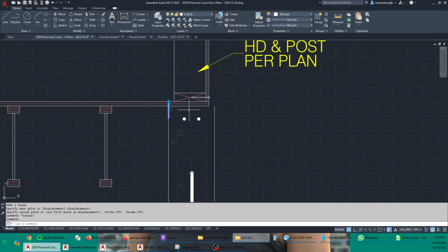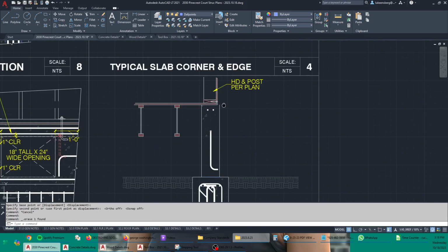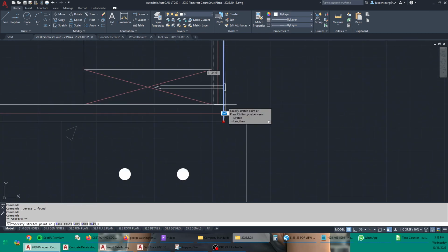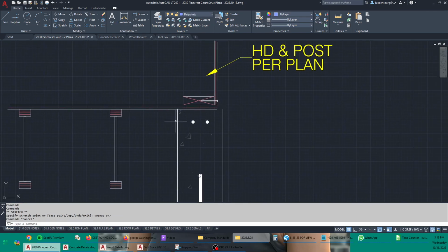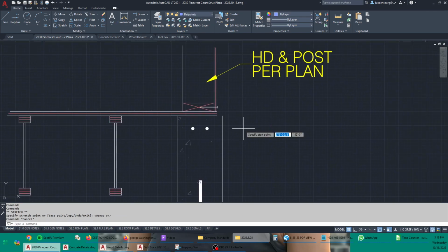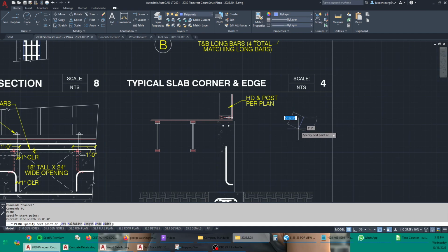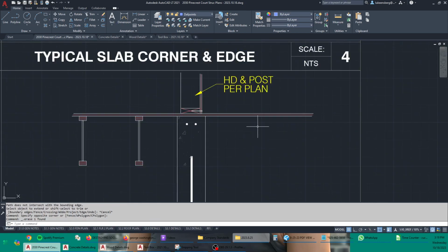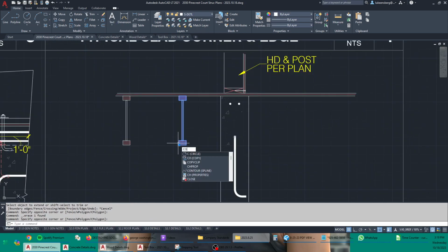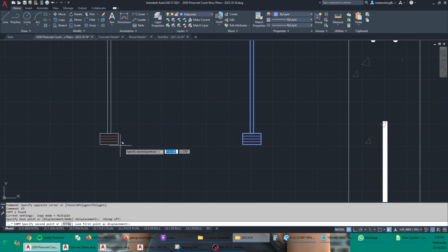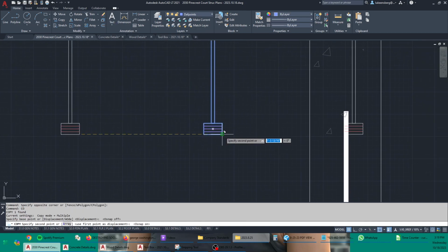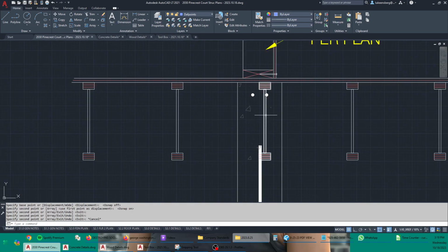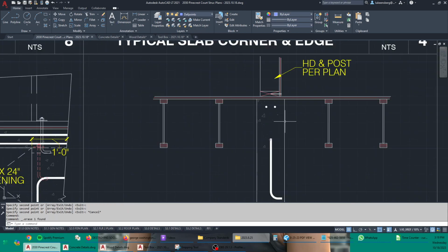This, we don't need that. And then this, let's move this up. The floor sheathing. Remember I said there's floor framing on both sides of the wall, so I'll extend out to that drawing aid I just made, boom. Right, and then we'll copy some more joists. I'm going to use the previously existing joist spacing to help me copy over, right? Those are all 16-inch like that. And then there won't be a joist right in the middle of the concrete wall.